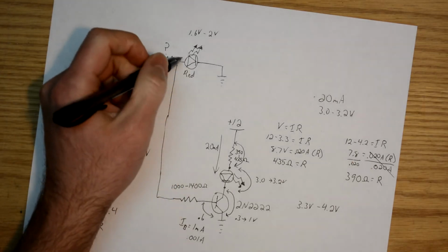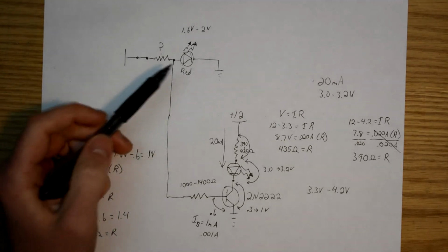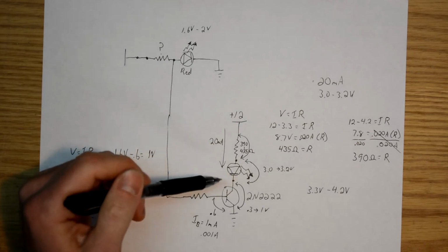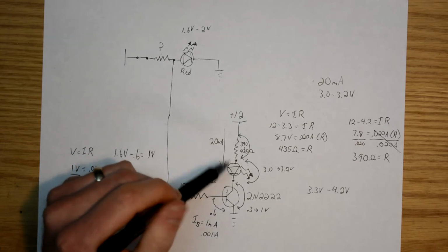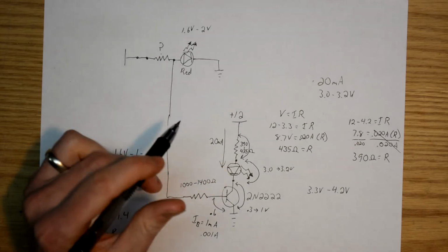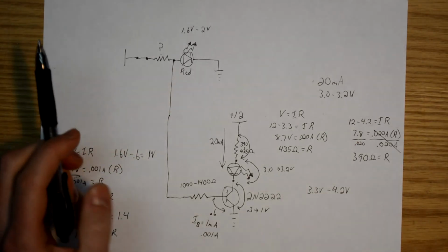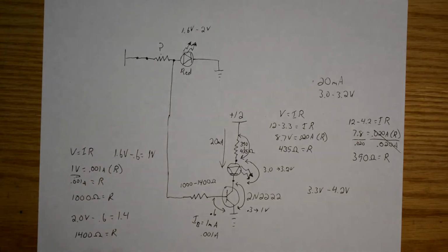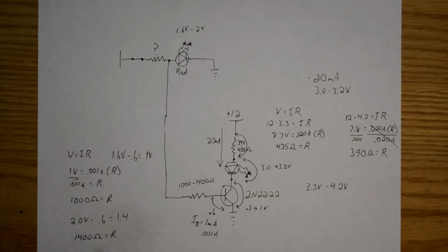Like I said, this resistor up here is a little bit multiplexed, so he may need to overdrive this LED a little bit, which should be fine. You may have to check the data sheet for that LED, but it should be fine to be overdriven for very brief periods of time, which may also be the case with this LED. It may be being overdriven so they can be multiplexed and still have adequate brightness. So hopefully this helps him out. You may see some additional comments if he has a little trouble, but hopefully there's nothing too advanced here.